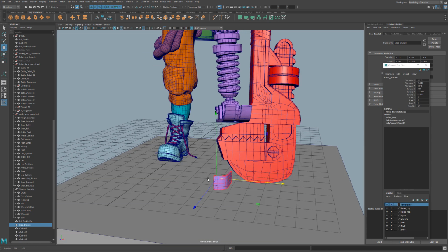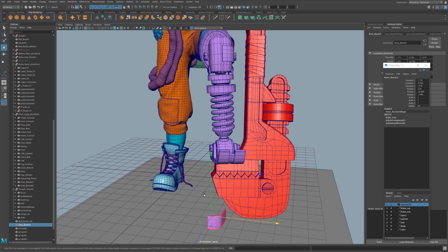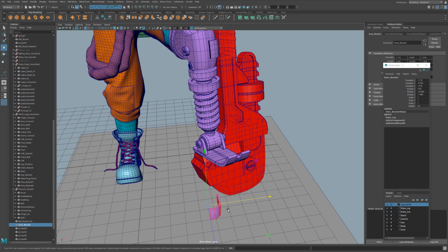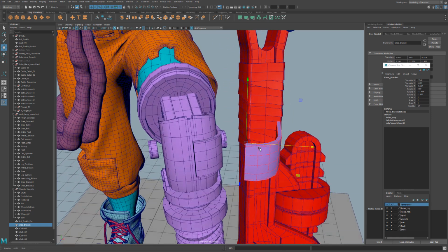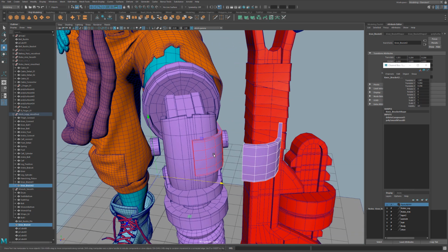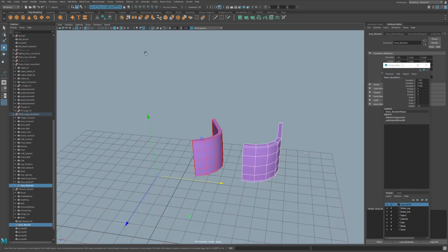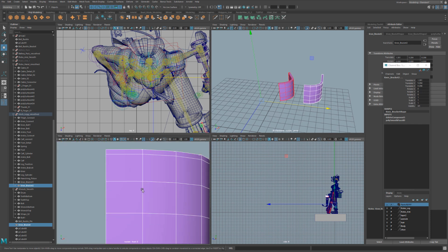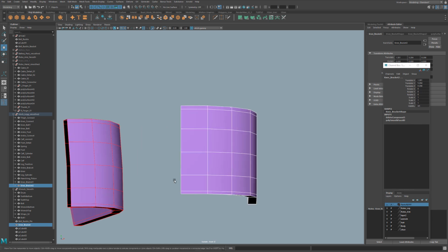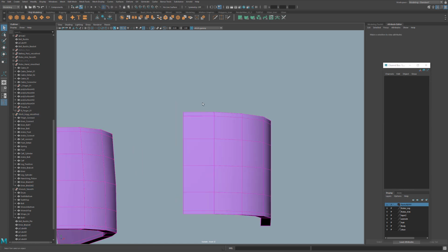So what I like to do at this point, this is pretty far from this piece. So what I could actually do is hold down V, and I just vert snap within the vicinity, and I know that it's somewhere close in 3D space, and then I can just create an offset here. And then I'll select both, do Shift I to isolate, and I can go ahead and model the changes. I'm going to go in here and do Shift I on the front, and I have this front view where I can work. So I'll quickly go ahead and do some modeling updates to this piece.